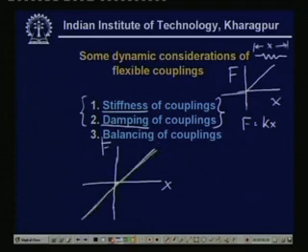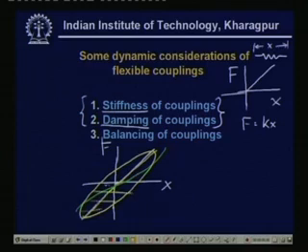But if it is non-linear, which may sometimes happen, then it may be something like this. Then when there is damping present, whenever you give excitations to it, it traverses one loop per cycle, which is known as the hysteresis loop. The area of this hysteresis loop governs the damping inside it.